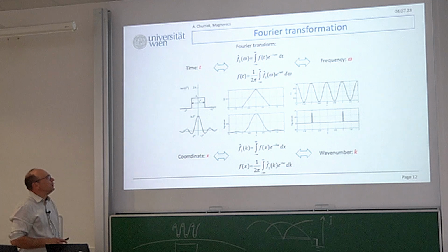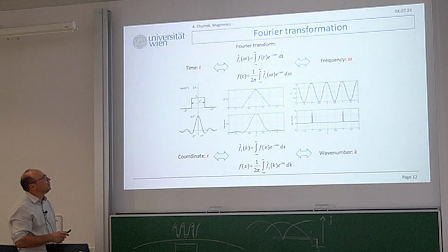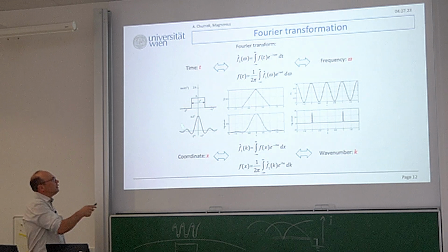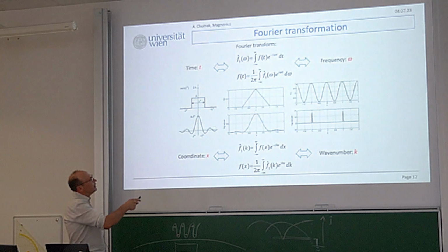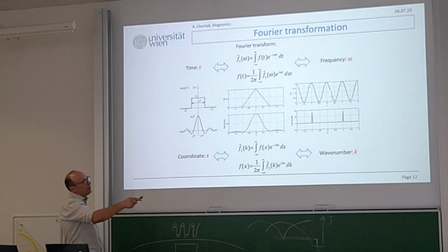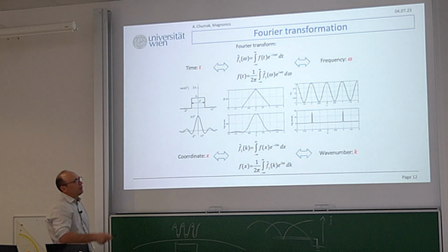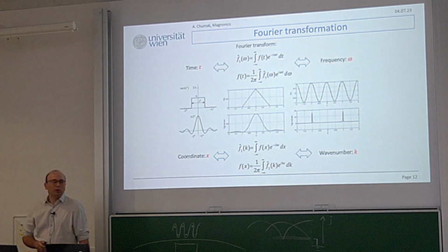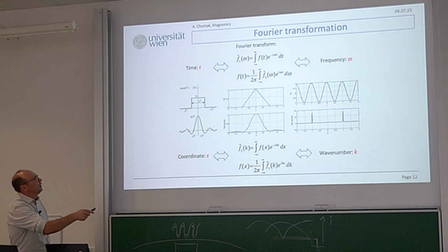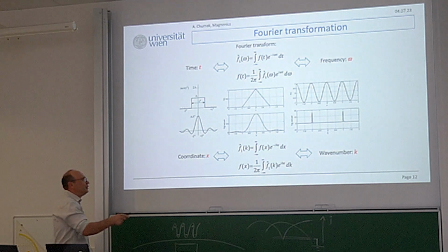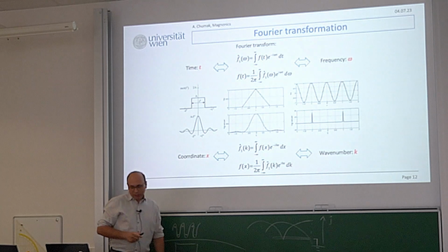Just keep in mind the simplest formulas for the Fourier spectrum. Yeah, so if you have a rectangular antenna, then you should expect something like a sinc function. This is closer to meander, yeah, when you have periodic excitations, then expect something like a delta function. It means that only a given k will be excited. If you manage to create an antenna with a triangular distribution of field, you'll have something like this. Good.